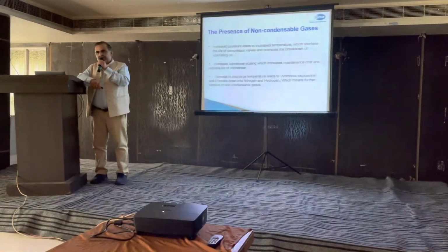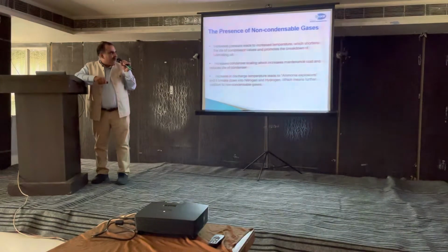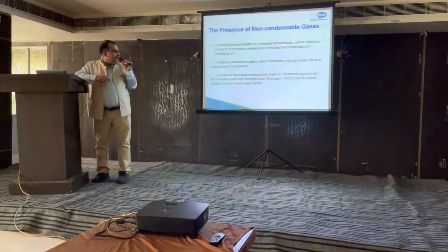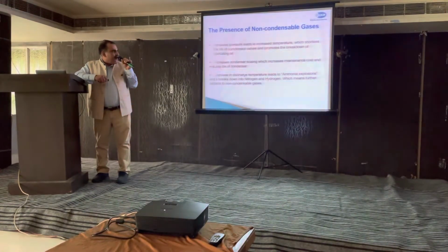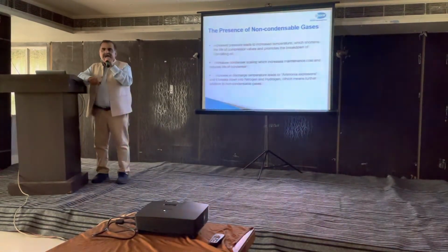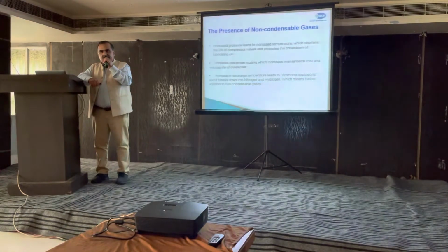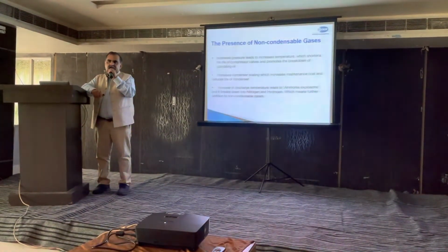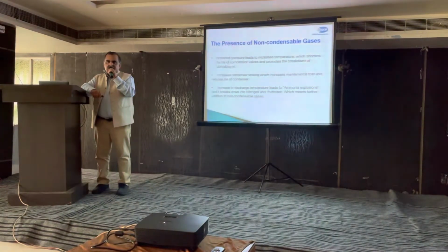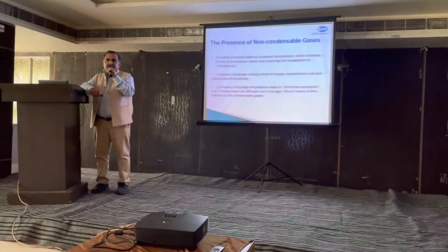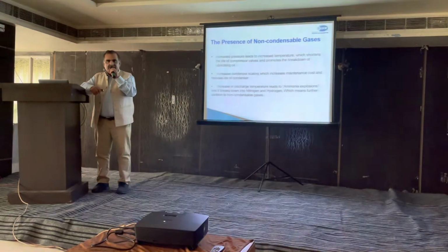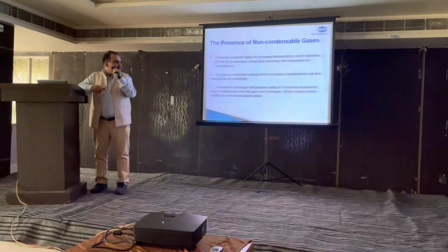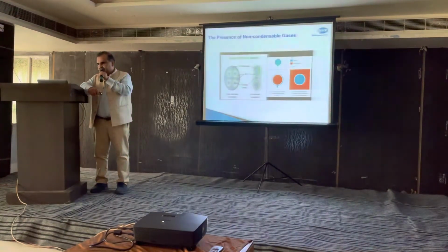One more possibility is ammonia explosion due to high temperatures in the discharge line. Ammonia, as you all know, is a combination of nitrogen and hydrogen. So due to high temperature, it is possible that this ammonia can break into nitrogen and hydrogen. That will make the two gases present, and it will lead to an increase in discharge pressure, because both these gases are non-condensable gases.